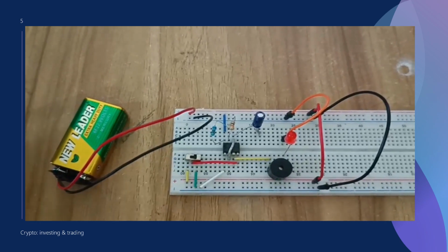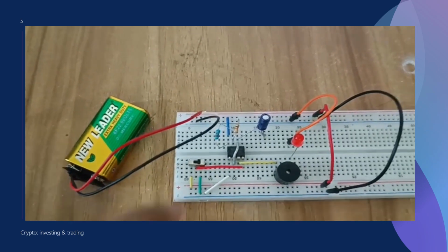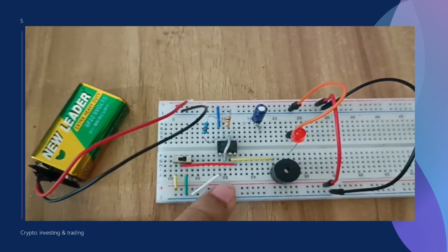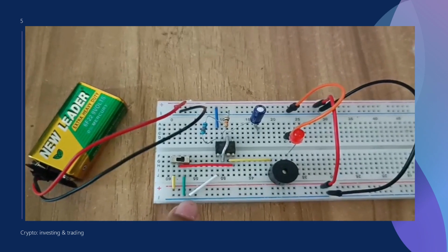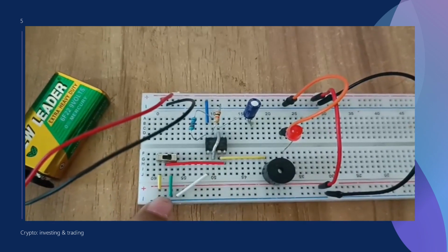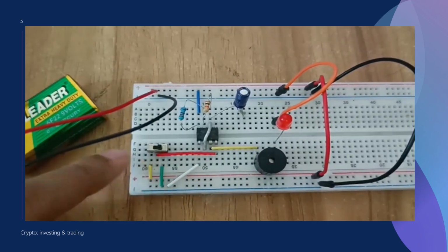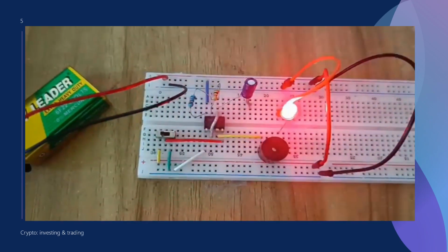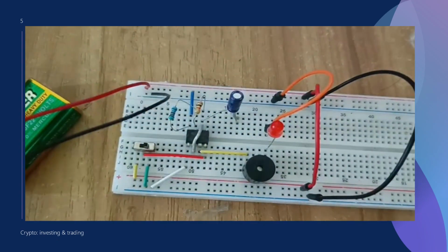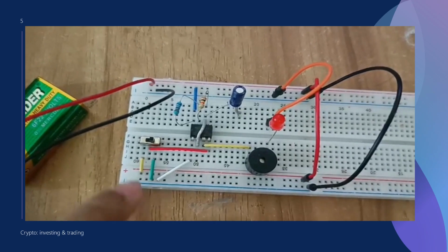So this is the hardware implementation of an intruder alarm. It utilizes a 555 timer powered by a 9-volt battery. The VCC terminal of the 555 timer is linked to the positive rail, while pin 1, ground, is connected to the negative rail. The reset pin of the 555 timer is also connected to the negative rail. Upon detection of an intruder by the motion sensor, the reset pin of the 555 timer is briefly connected to the positive rail. After that, the alarm, consisting of a buzzer and LED, stays on until reset by the appropriate authority.